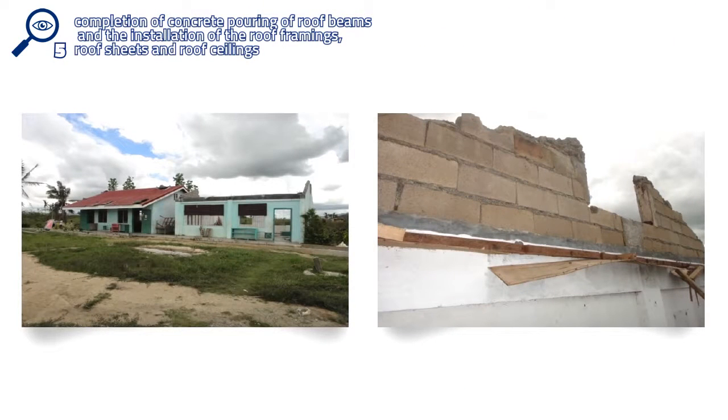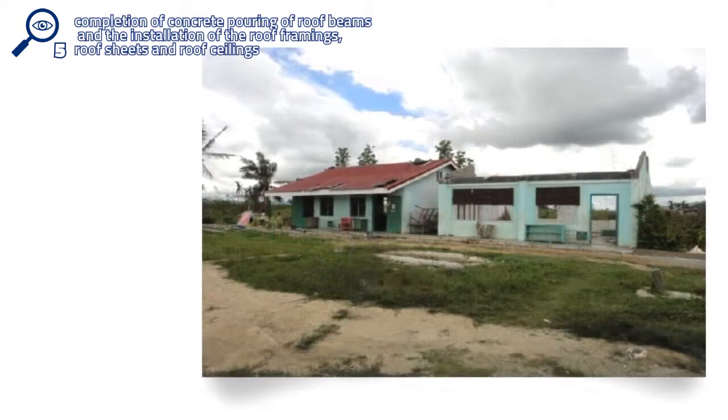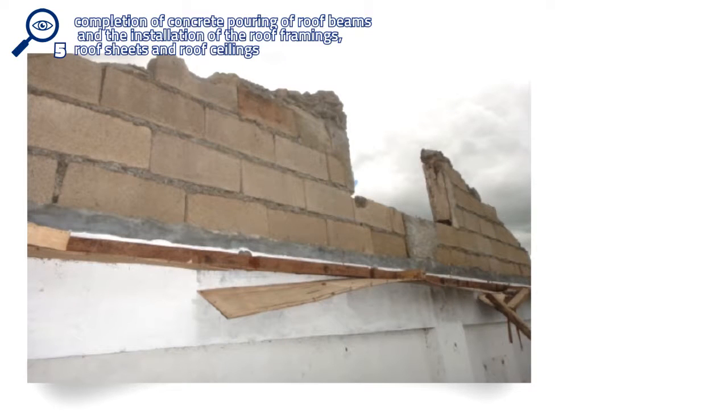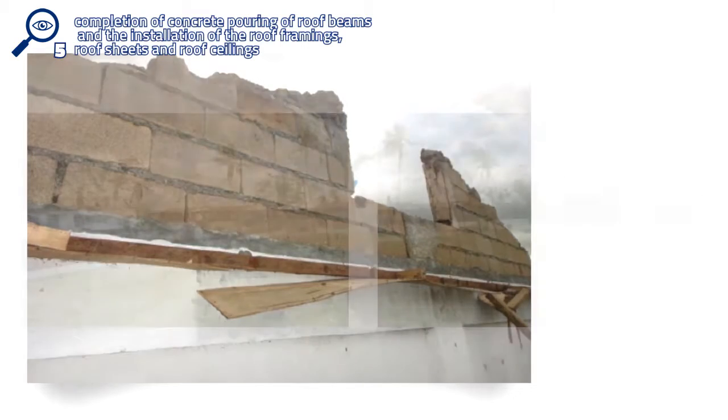Examination of many classrooms damaged by Typhoon Yolanda back in November 2013 showed that much of the damage was caused as a direct result of failure to anchor the roof trusses. This point is clearly demonstrated in the photos. These show 2 adjacent buildings, one of which was severely damaged. The roof cover and ceiling were completely blown off, whilst the other building of similar design was relatively undamaged. Inspection of the damaged classroom showed that the roof trusses had not been properly anchored to the beams and that the walls did not have adequate steel reinforcements.